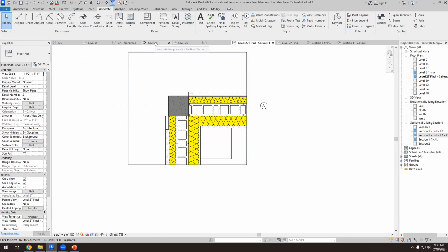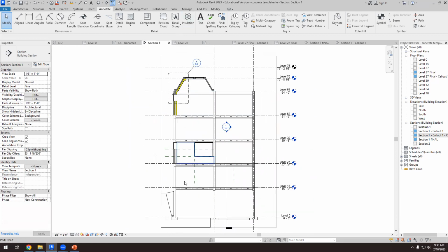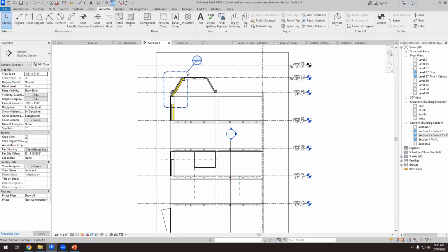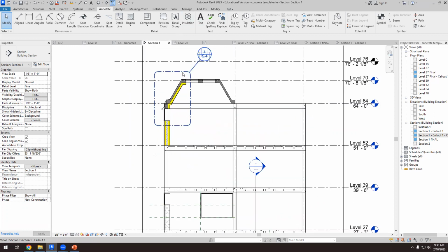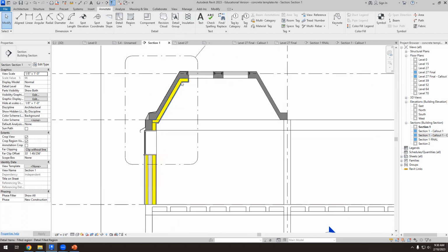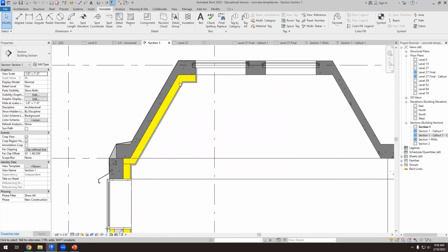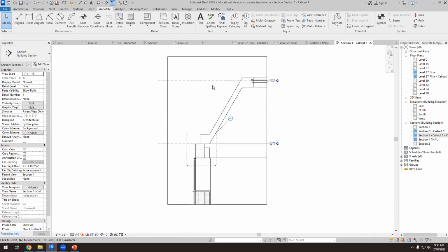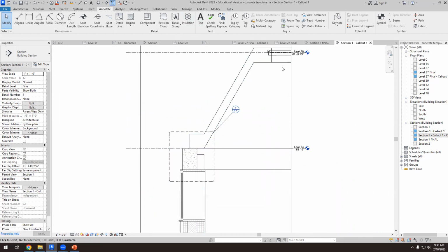And then with the section, show me that we have the section from the basement up to the roof, and at least one call out. Don't do this in the section, do all that stuff with the regions in the call out, not here. Okay, so in this call out, I want to see that you have the thermal insulation there.